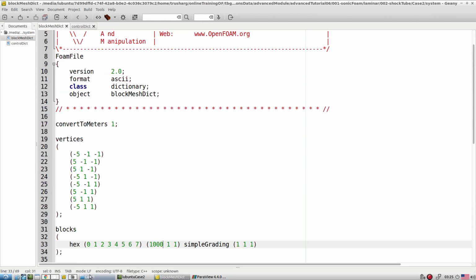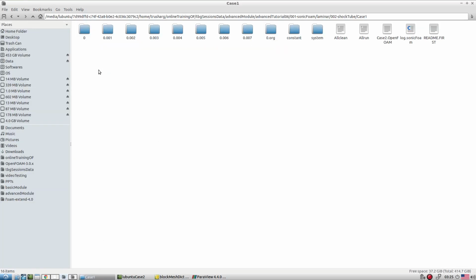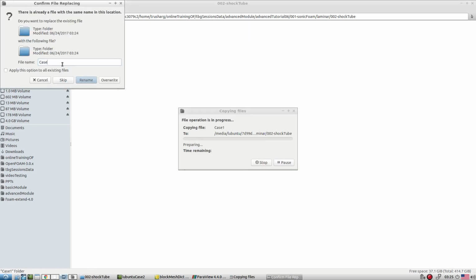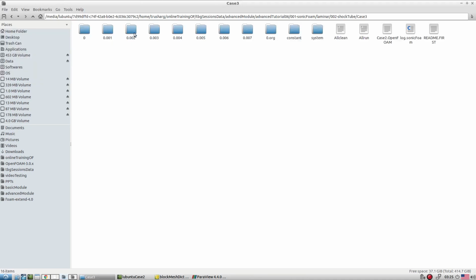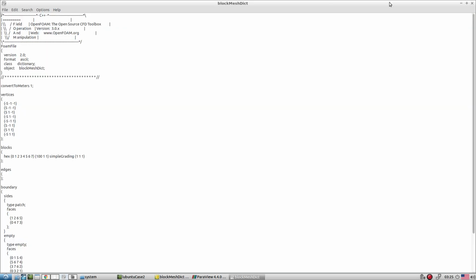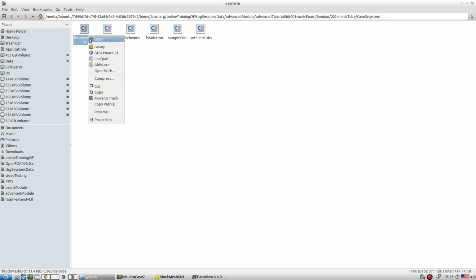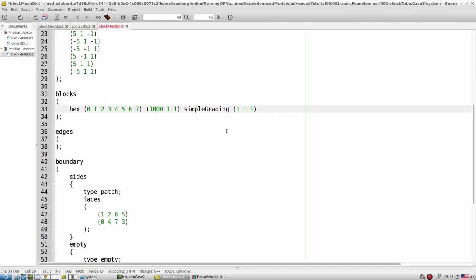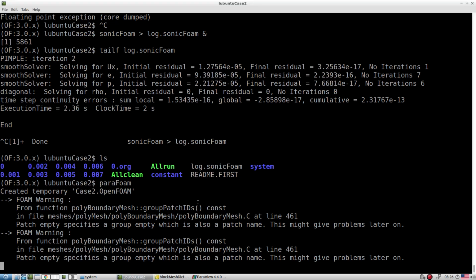Okay, so let's generate very quickly the third case. It's not going to take too much time, so no worry. Let's say third case. In the third case, what we're going to do is generate an even much finer mesh. As compared to this one, where I gave 1000, let me give something like 10,000 elements in that direction. Okay, 10k, fine, save.